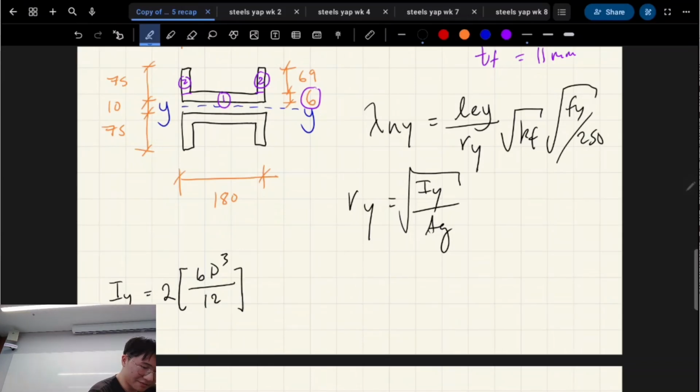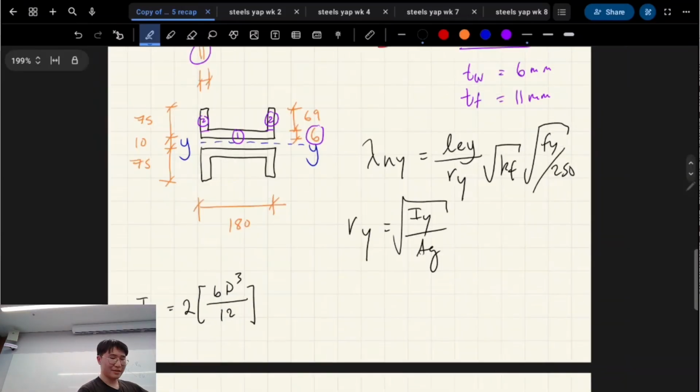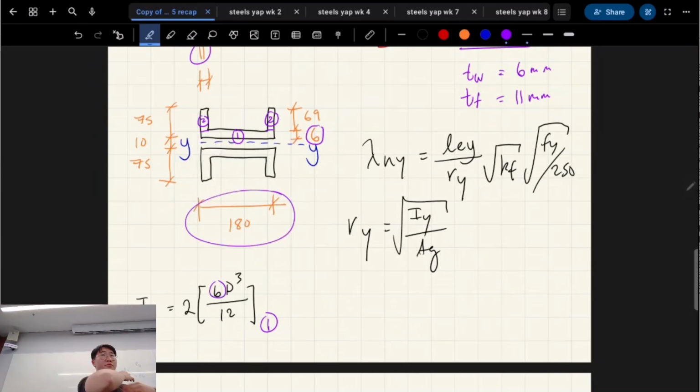Here's the moment of inertia for a rectangle, and we're doing this for shape 1. Okay, alarm bells, right? BD cubed on 12. That shouldn't be for IY, correct? Not necessarily, because we've orientated everything 90 degrees so the y-axis cuts through horizontally. When I say B, I'm referring to the left-right dimension. When I say D, I'm referring to the up-down dimension. So this should still check out. We're still taking everything relative to the minor axis, okay?